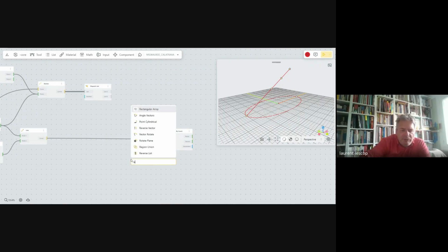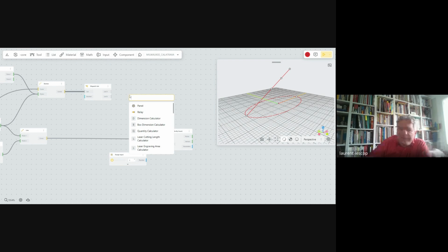So I will do a range input. I didn't explain it, but what I do is I double click on the screen, and then I just type the phrase, because with practice, you know that you don't have to go to the menus all the time. If you double click and you need a line, then you just type line, and so on.